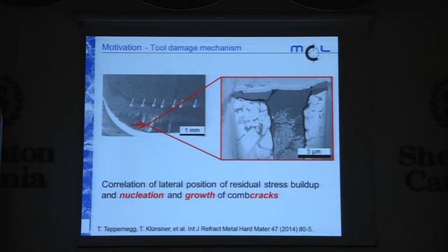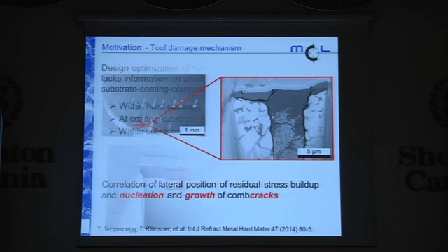And we could show also that this area with this tensile residual stress buildup is correlated in lateral position with the emergence of the first cracks that emerge in those tools. So we were able to show that this buildup of tensile residual stresses is very, very crucial for the degradation of the tool.